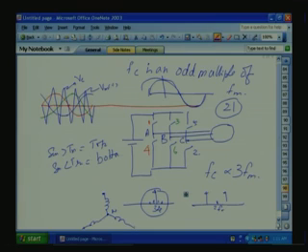Okay. Now, this way we can use sine triangle PWM. Now, the purpose of the PWM is that even though we are controlling the voltage, what we require is nearly sinusoidal current. With the switching, the ripple current follows like this.